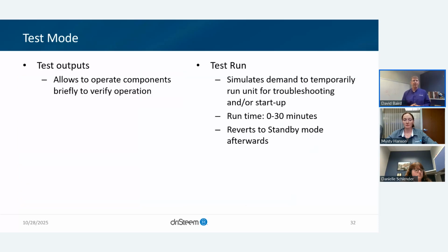Another helpful piece from a diagnostic standpoint is the test mode. Test mode allows you to run everything, or I can test specific pieces. Let's energize the fill valve, make sure I can hear the click and it's working. Energize the drain valve, grab an individual component, or allow the unit to run regardless of demand signal for a period of time to just check and make sure everything is good to go on it.